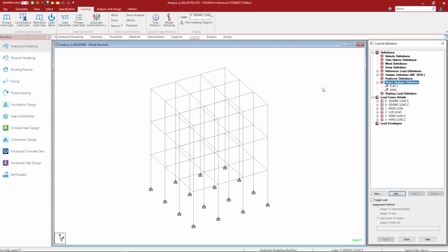Now, if I were to take a look at the AISC 360, I can see that applying the stiffness reduction to some members and not others can, in some cases, result in artificial distortion of the structure under load and possible unintended redistribution of forces.